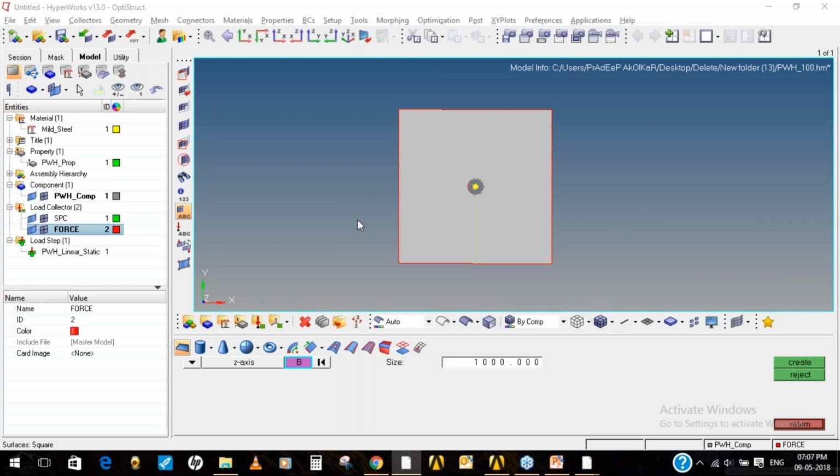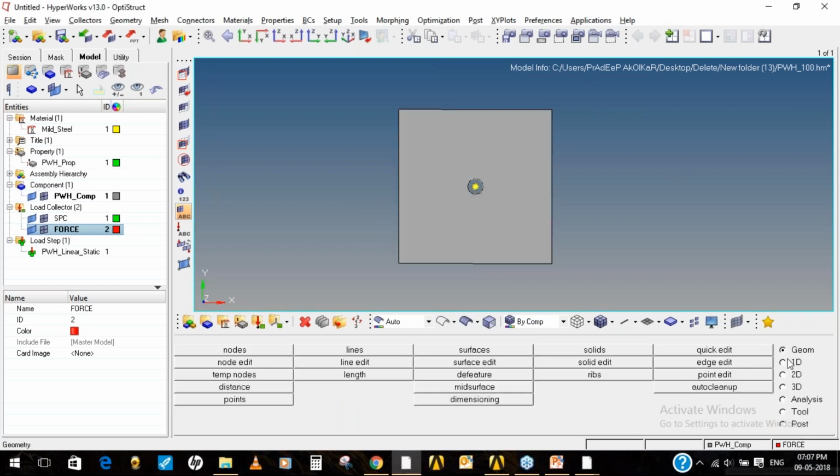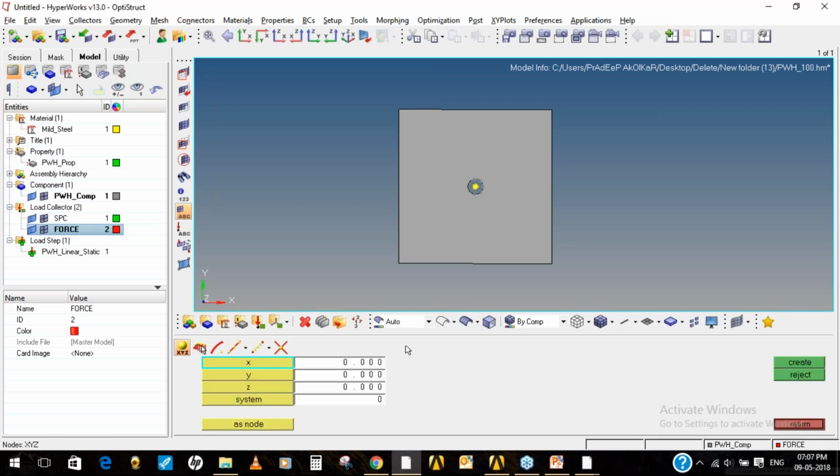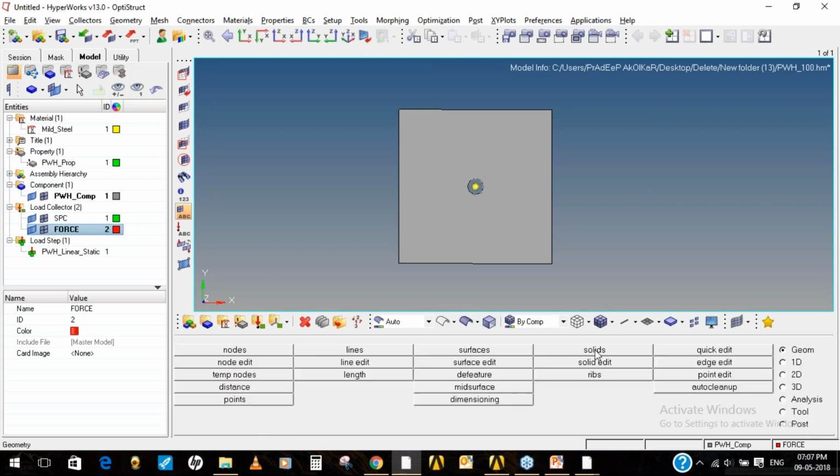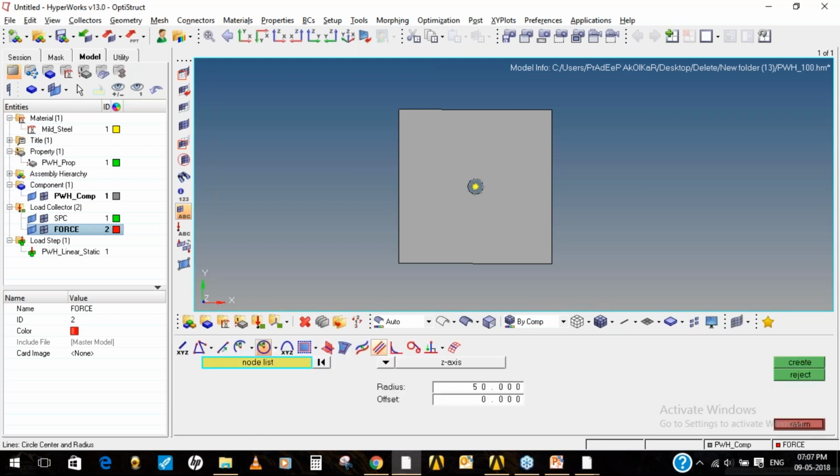Rajat, is your query answered? Okay, you need for a rectangle. So in the same way, if you're having a rectangle, you can go to nodes. You can create four nodes. However you're having the dimensions of your nodes, you can create. You can give the inputs for the coordinates for your nodes, and then you can go to lines. You have seen this option, that is linear nodes. So you can go to linear nodes. You can join the nodes and create a line geometry for that rectangle,